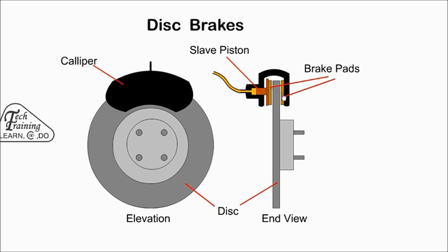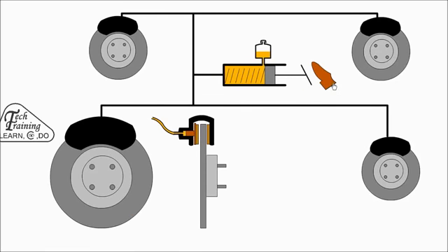With a hydraulic system, when we supply an incompressible liquid, the force is transmitted throughout the fluid. By adjusting the size of the pistons, we vary the available force and the distance travelled by the slave cylinder. Here we see the master cylinder with a reservoir for brake fluid on top. When the pedal is pressed, the piston moves forward and closes off the inlet from the tank. The fluid is then pressurized and activates the slave cylinders.